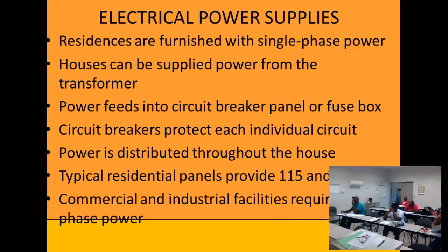First of all, this wire is insulated. May not look like it, but it is. Painted on enamel. It's going to heat up, it's going to melt off. Instead of going around and around, it's going to go right across it when it melts. Now it doesn't have any resistance. It's what we call a dead short. It will destroy itself.